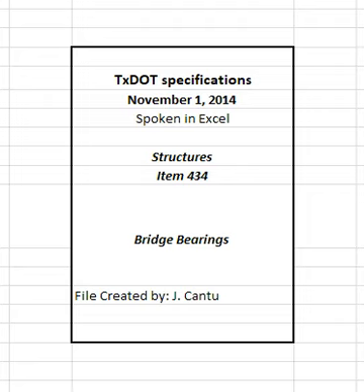Obtain approval for each elastomer formulation before use on department projects. Submit certified test results to the Construction Division to pre-qualify and obtain approval of a particular formulation. Show actual test values obtained and the required values for the physical properties, heat resistance, and compression set of the elastomer when tested for compliance with the minimum requirements of AASHTO M251, Table X1.1.